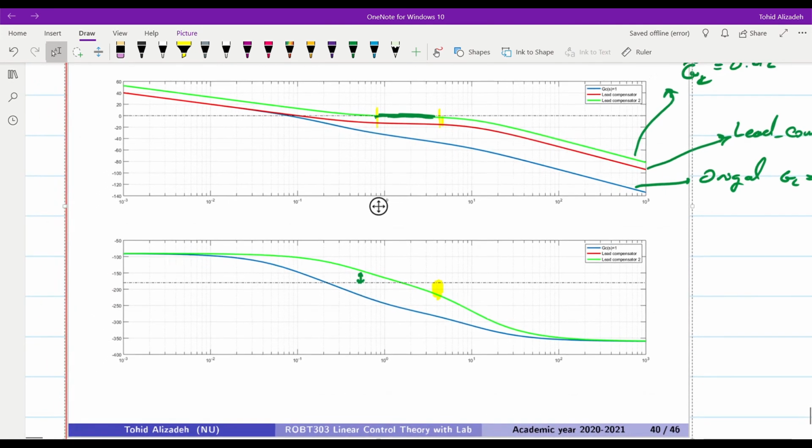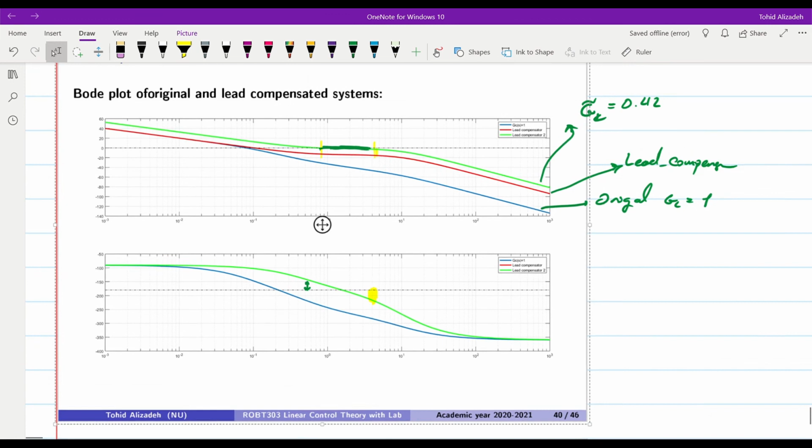Alright, so I think that's all for this video. I hope you have learned about non-minimum phase systems, how to deal with such systems, and how to design the controllers, and you have seen the limitations that we have in terms of the maximum achievable crossover frequency. The phase value for such systems goes quickly towards negative values, and the amplitude plot at some point becomes flat. So there will be a jump in the crossover frequency if we try to increase it above a given value.